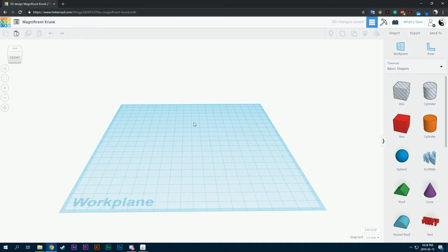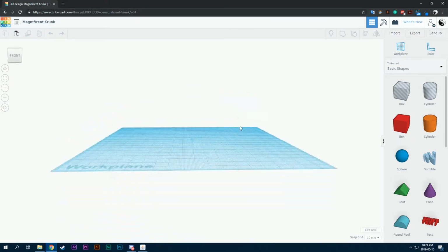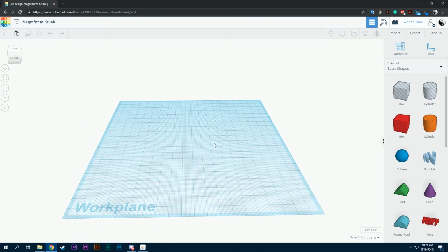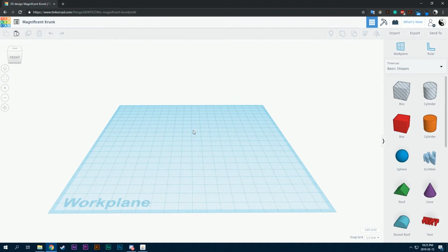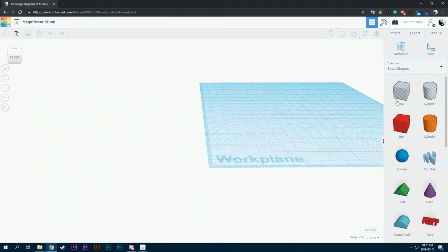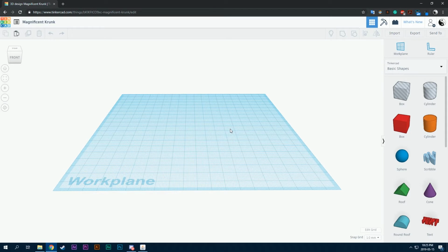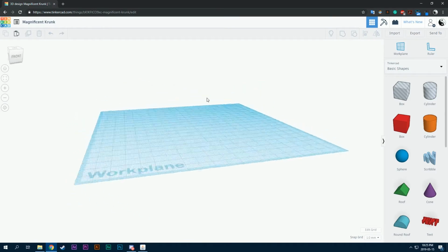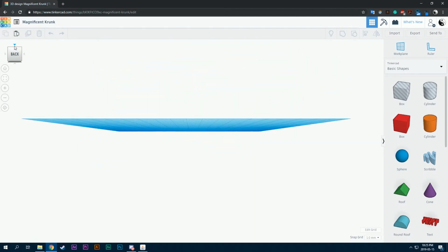So if you right click, the right button of your mouse, you can move the plane around and view your model from different perspectives, which allows you to see different angles. And if you use your scroll wheel, rolling it up zooms in, and rolling it down zooms out, pretty obvious. And if you click on your scroll wheel, it shifts the plane, so I can move it from left to right or up and down, but it won't change the angle I view it from. So that's middle mouse click, just clicking on your scroll wheel. Once you get a flow with these controls, you can go precisely, so it's not that hard.